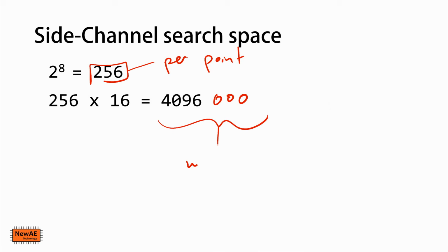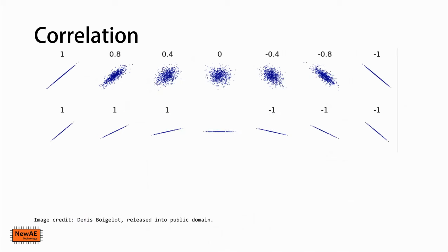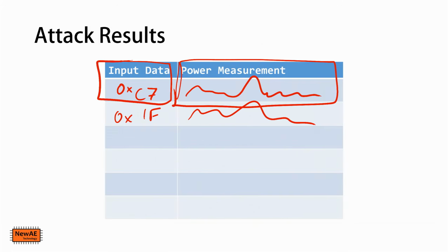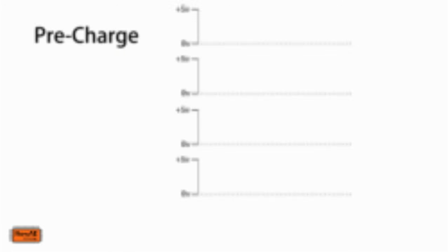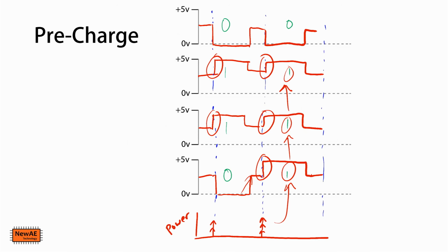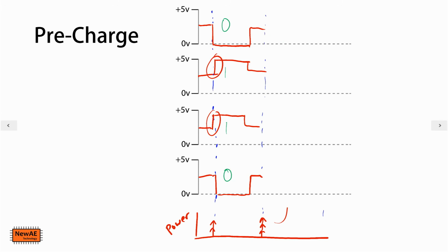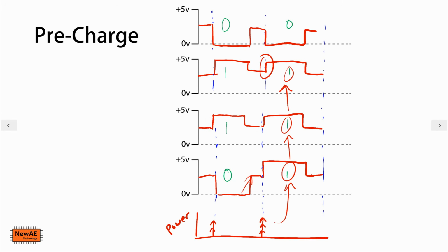So it's worth pointing out two things. Things like credit cards, which are also smart cards, have had a lot of money put into making sure this leakage is as small as possible. So looking back at this Hamming weight leakage, for example, one thing you could do is simply have complementary lines that always switch in the opposite direction. So if I draw in blue here, I could have the same pre-charge, but I could always have a line that's doing the opposite of whatever this one line's doing.